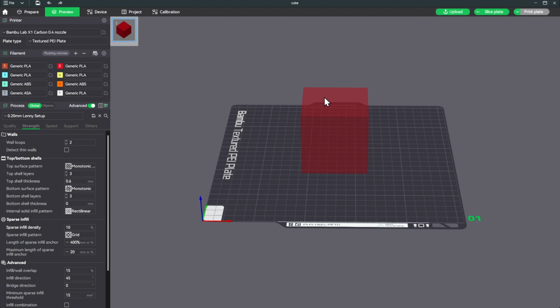The infill pattern does affect the strength of the object. Maybe it's shear strength, it's compression strength from the sides, and different things like that. So each one of these does have an effect on that and will change as your objects change, and as you change these different infill patterns, the properties of them will change. And we'll go over each one of these, and I'll give you a couple of real brief suggestions on when to use them and what the pros and cons of each one of these are.